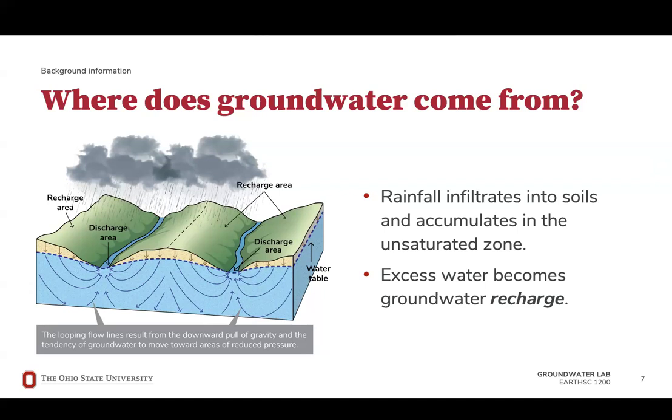As water percolates through the soil, it reaches the saturated zone, where the water table is located. When all the soil is saturated, excess water becomes standing water or runoff. The rate of infiltration is expressed in inches per hour and is affected by soil grain size, slope, vegetation, and rainfall intensity. Some materials, like granite, are impermeable and allow almost no infiltration, while others, such as limestone and sand, have high permeability and can hold large amounts of water, sometimes creating underground aquifers.